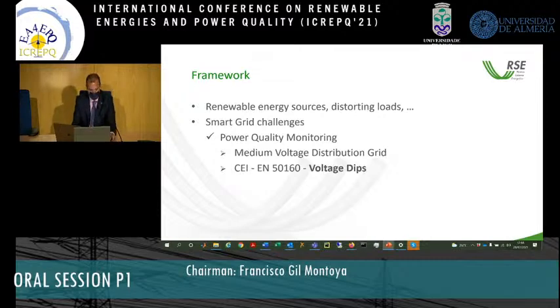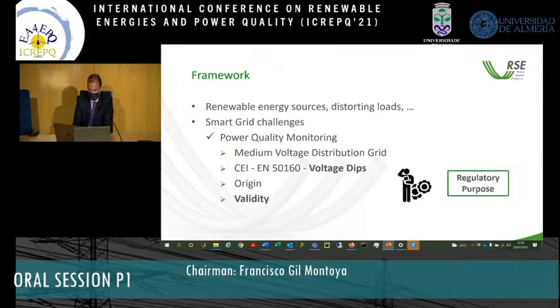What is a voltage dip? It is a temporary reduction of the voltage supply under 90% of its nominal value. And when we talk about voltage dips and we want to use them as an index for regulatory purposes, we have to pay attention to origin and especially validity.